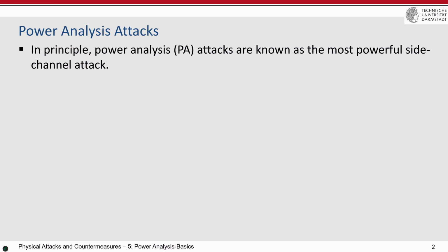Actually, they are considered the most powerful side-channel analysis attacks. If we compare them to, for example, timing attacks that you have seen before, in timing attacks you usually are able to measure the entire time, or the time of the entire encryption. But with power analysis, you get some information for every clock cycle, now what the device is doing. Of course, not exactly what the device is doing, depending on the adversary model and the attack, but you get much more information compared to timing attacks.